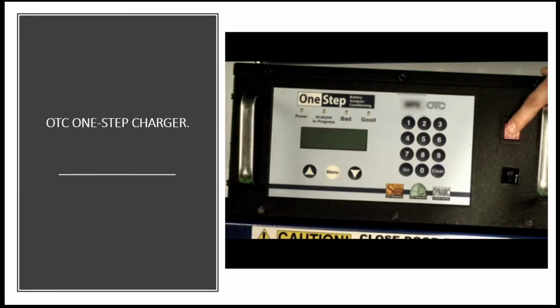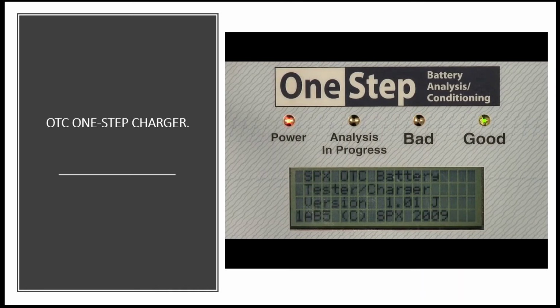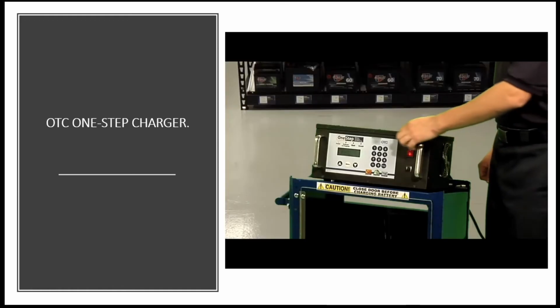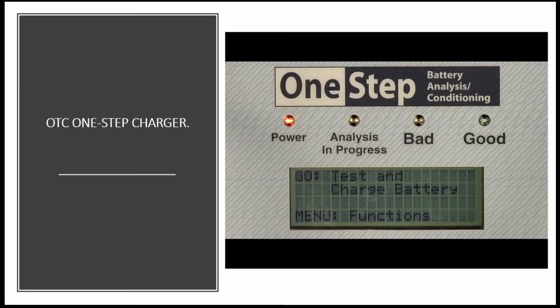Press the on-off button to power up the battery charger and analyzer. The power status light will light up. After powering the unit, the first screen that appears is the language selection. The default language is English. The unit will default to English each time it is powered down. Spanish and French are also available. Press the number 2 key for Spanish and the number 3 key for French. To continue in English, press 1. Press Menu to access the Functions menu. These options are factory set and do not need adjustment.